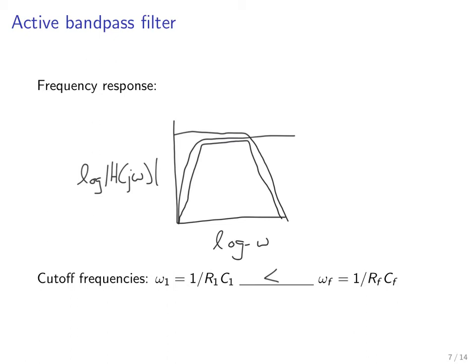Now, I'll note that in this case, all of the components factor into cutoff frequencies here, so it is not possible to independently change the cutoff frequencies and the gain of the filter in this case. There are not sufficient degrees of freedom to do that.